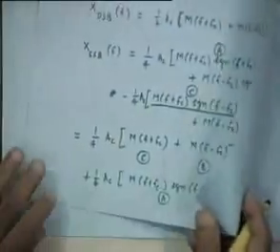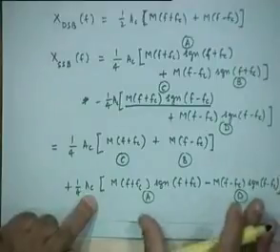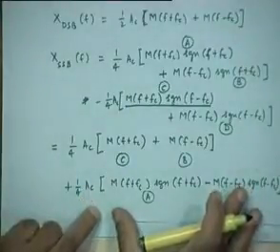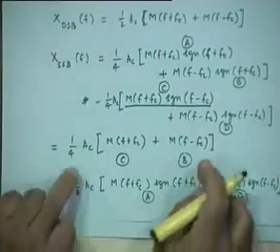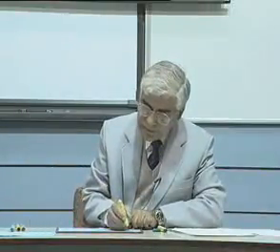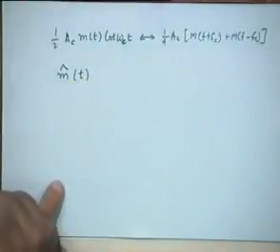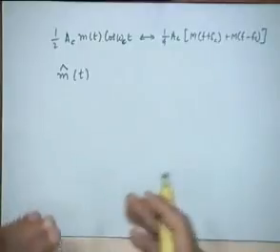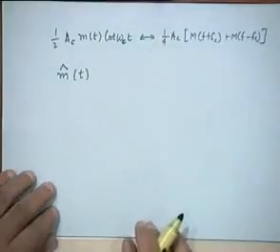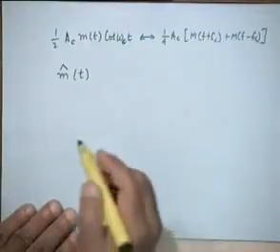However, what the second two terms will amount to is not very clear right now, right? What will be this part of the function is not very clear. So let's try to understand this part. This part is clear in the time domain. Okay. So now let's start with this. This is where the Hilbert transform comes in very handy. Remember, the Hilbert transform is defined in terms of the signum function in the frequency domain, and we are having signum functions here. So there is a relevance here of the Hilbert transform, use of the Hilbert transform.